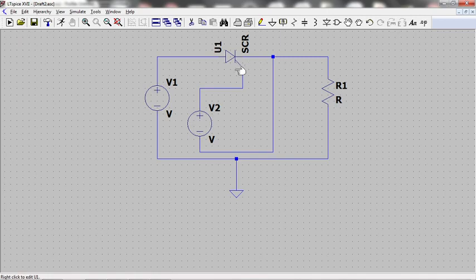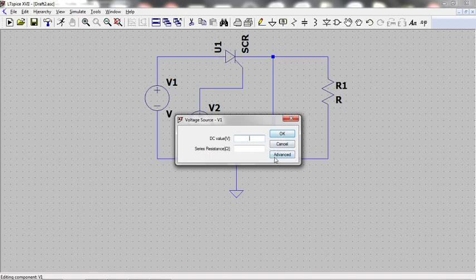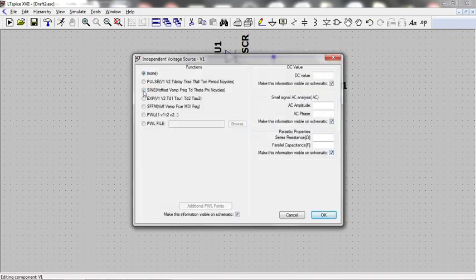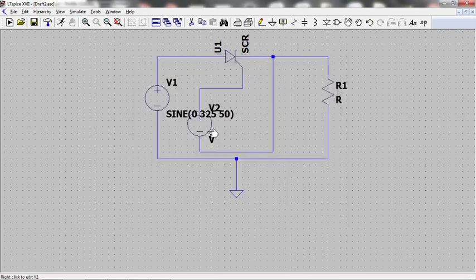Okay. Now I am using this voltage source as a power source. So you go to advanced, sine, because it is a sinusoidal voltage source. Offset is 0, amplitude I will choose 325, that is the maximum amplitude, frequency 50 Hertz, delay, the rest keep as it is. Here I am choosing a voltage source of 50 Hertz whose peak value goes to 325 in the positive peak, as well as in the negative peak it goes to minus 325. Such a voltage source I have chosen.